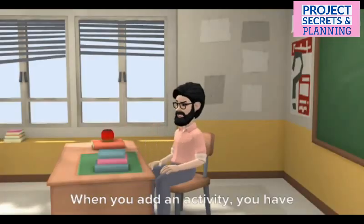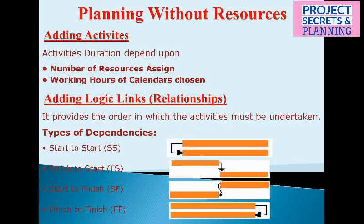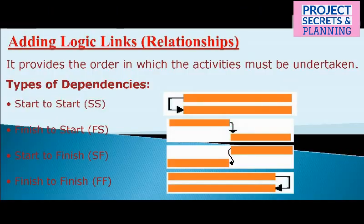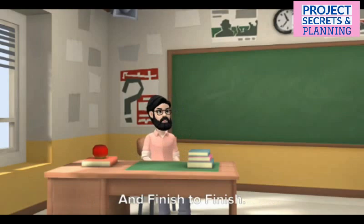When you add an activity, you have to estimate its duration and the number of resources to assign. Then you make relationships between activities. What do you mean by relationship here? There are 4 types of relationships between activities which make your schedule logical. Start to start, like 2 activities starting at the same time, in parallel. Finish to start, like you cannot do lean concrete of a foundation before its excavation, so excavation will finish and allow the start of lean. Other logics are start to finish and finish to finish.